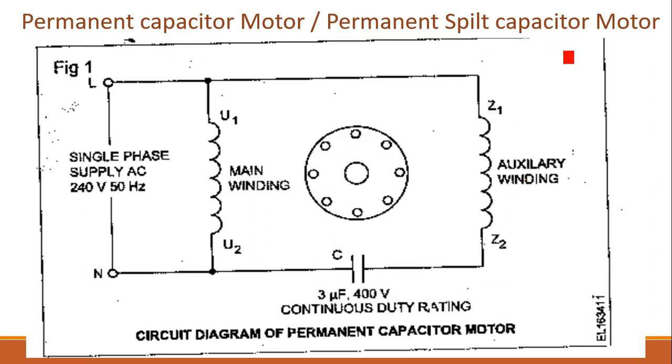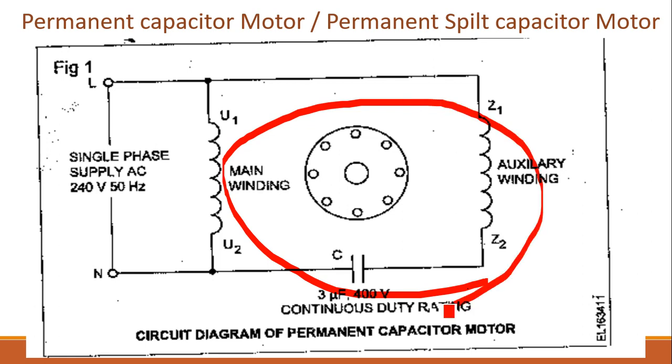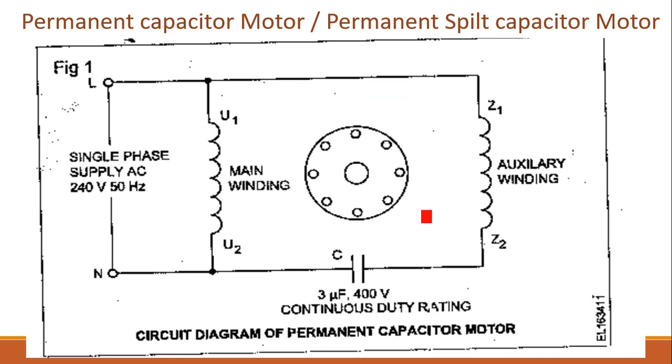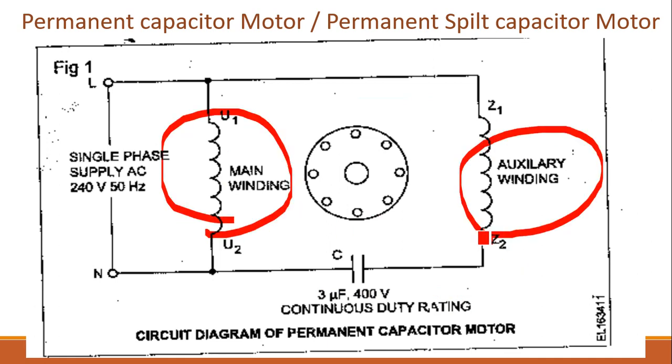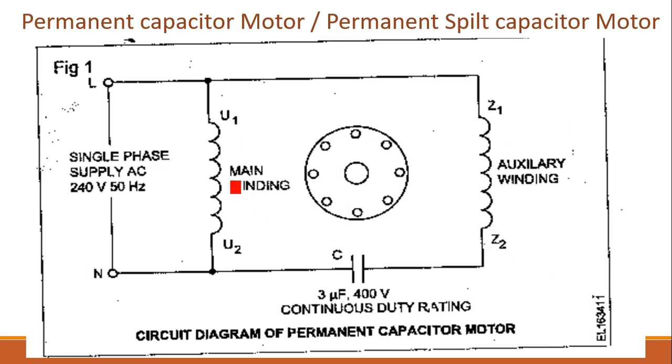Also, in single phase motors without the centrifugal switch, the windings are known only as main winding and auxiliary winding. There is no running winding or starting winding, because both the windings are used continuously, and we cannot say one is the starting winding or the running winding, because both are available during the entire operation of the motor.